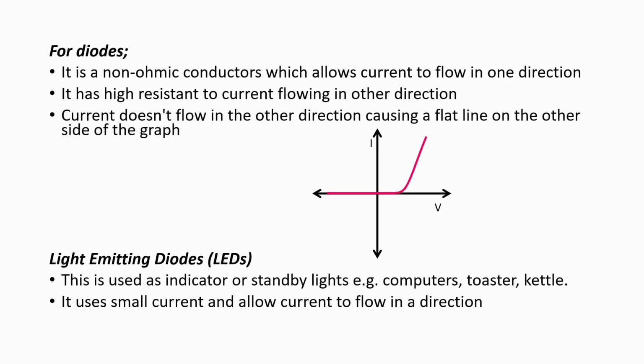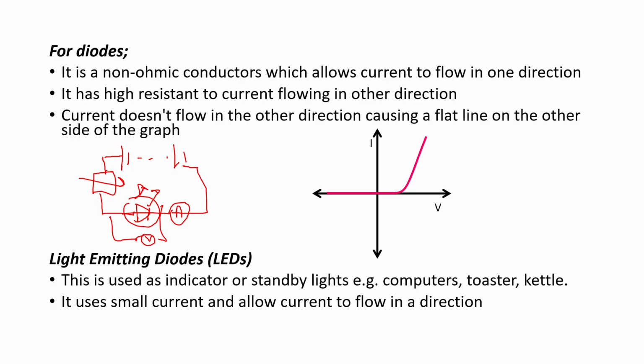Excellent, good, known ohmic conductors, that's all looking good, nice graph there. And again, I like the fact you put the LEDs in here. If I do this in school, I do an experiment very, very similar. I start off by just getting them to put an LED in a circuit and realize it only works in one direction. And then you can do a nice little experiment with a light emitting diode, an ammeter in, put a voltmeter in, and get them to actually plot this graph.